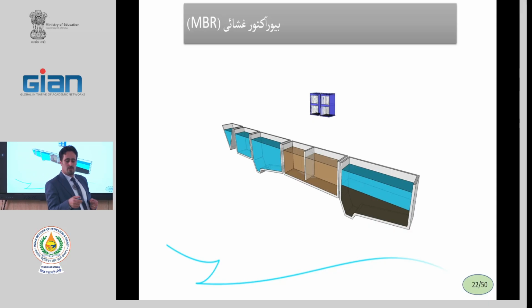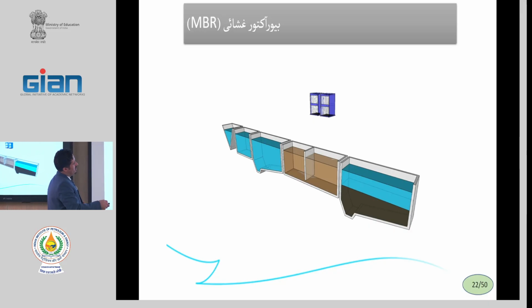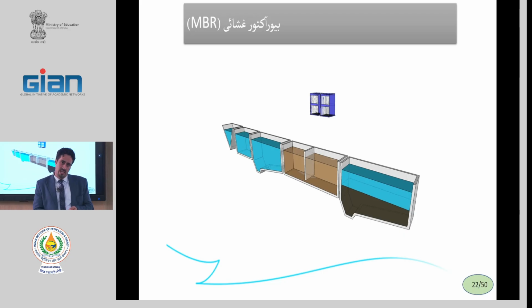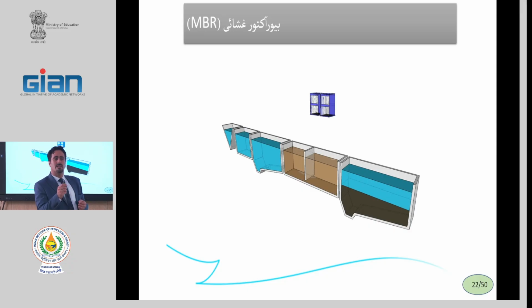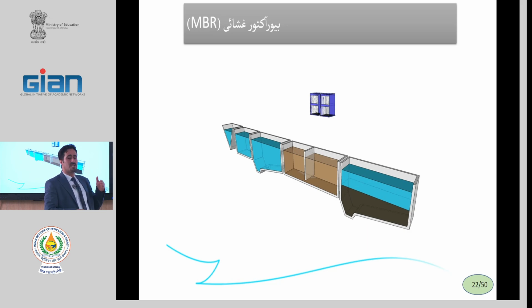The traditional method is the use of a precipitation tank or sedimentation tank. Because of the hydrophilic nature of microorganisms, the sedimentation is very slow and therefore needs a very big tank for sedimentation. Almost 1/3 of the treatment plant is related to the sedimentation of the microorganisms.